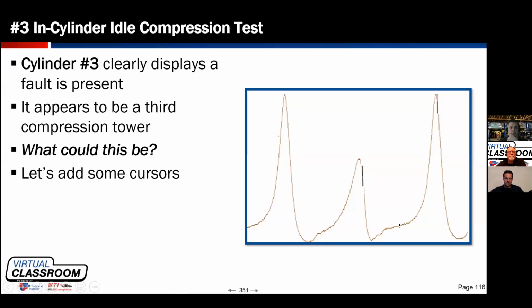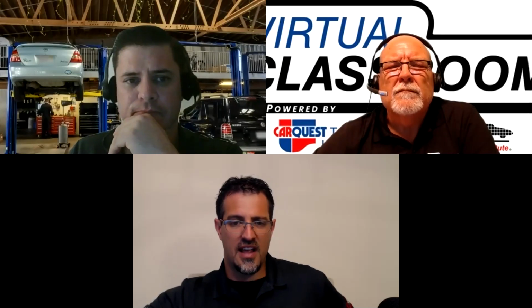What are you using for inches of water? I guess that is a tailpipe sensor. It's an absolute transducer that works just like the intake manifold transducer or the in-cylinder pressure transducer. It's just that it's scaled so tightly. It measures 25 inches of water as its max output. There's 25 inches of water in 1 inch of mercury, so it's 25 times more resolute than the vacuum transducer, but it functions the same exact way.